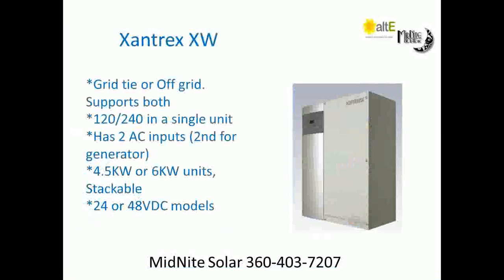So again, I want to point out generator support. That is a very neat feature for off-grid folks, and it's only available in the XW and the SMA Sunny Island. Magnum is working towards it. I believe they're going to have a new inverter out soon that will do generator support, but I also understand it's 120 volts only. I'm not sure of that for certain. I will look into that and have that information at a later date. Any questions on that, definitely give us a call.